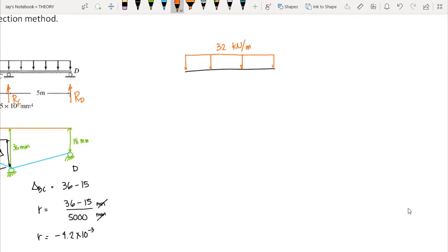So on the free body diagram, we would have here the right reaction of C. Okay, that's RCR. And the reaction of D, we have RD. And again, we have a moment CD, and we have here moment DC. Now take note, our moment DC here is equal to 0, correct? Because that is a roller support at that point. Again, we do not have moment when we have a roller or hinge support on the farthest right or farthest left. So in this case, we will be using the modified slope deflection equation for MCD.